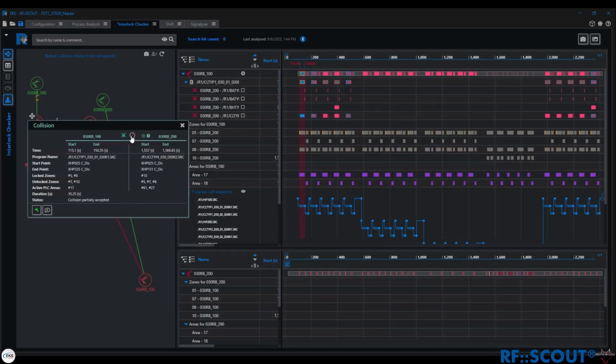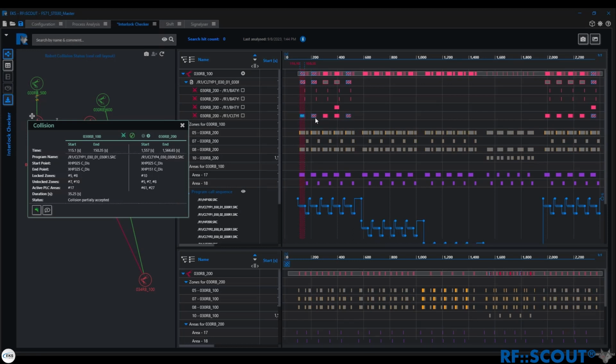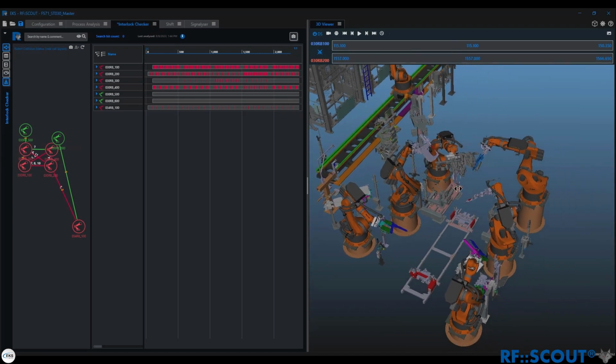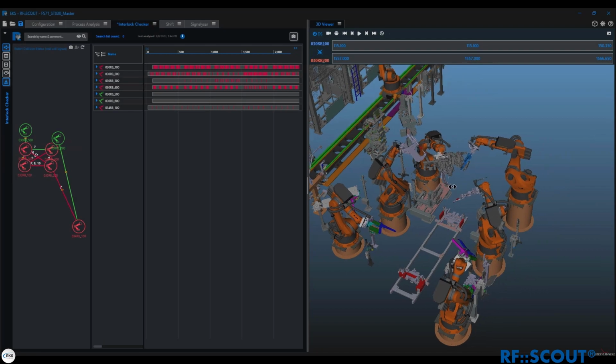As soon as one or more parts of them are accepted, these acceptances are also applied to all other collisions in the same grouping. There was also a change in the camera work. As camera work continues to evolve, we have introduced a new default camera. A short description of the change controls can be found in the camera tooltip. The most important key here is the Alt key in combination with the right or left mouse button.